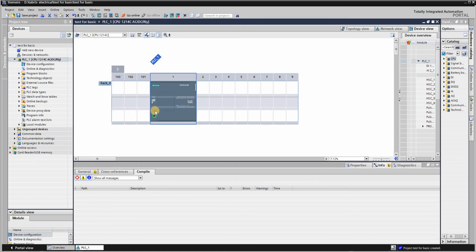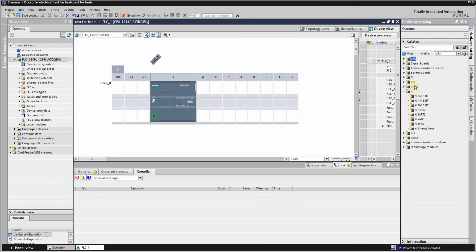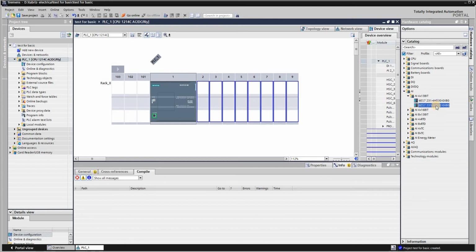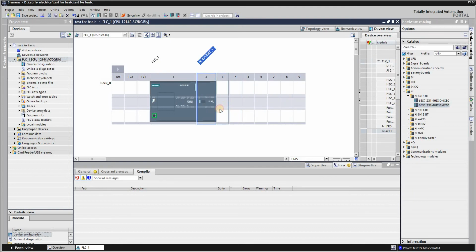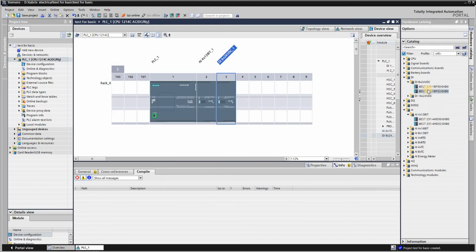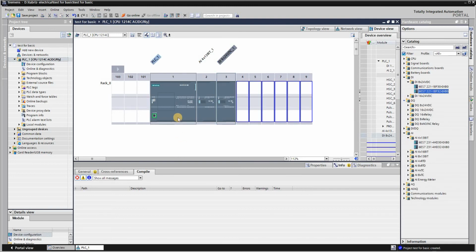Now that you have a PLC, we have to add analog inputs, outputs, or DI/DO modules. For this particular PLC, you can find the modules here. If you need to add an analog input, let me pull it so it's more clear for you guys. You have different categories, 13-bit, 16-bit. Just go ahead with the first one, 4-channel 13-bit. You just double click it, it will automatically assign. Now it's already there. Maybe you need to add DI, just open it, 16-channel or 8-channel, just double click it, and it takes the sequence there. So this is how it is with the PLC.